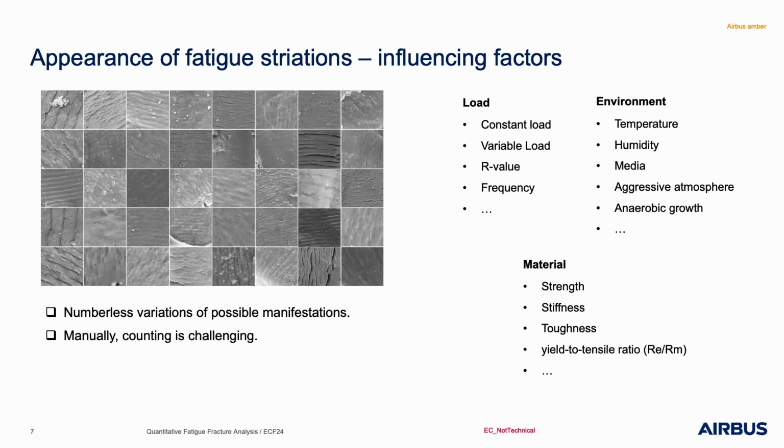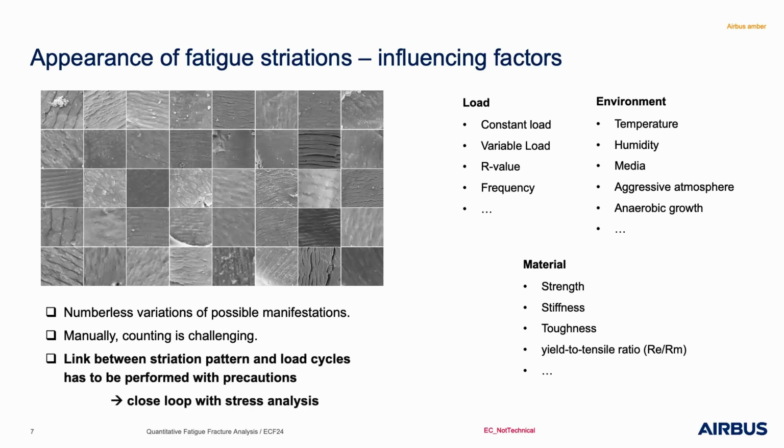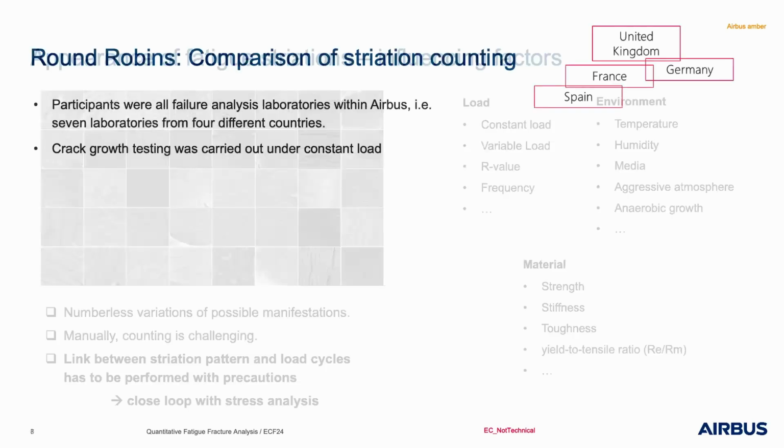Yes, and that's also a very important point, that the link between the pattern and the load cycles, because of these possible manifestations, has to be performed with precautions, that we are always in close contact with our stress analysis departments concerning the striation counting at the end.